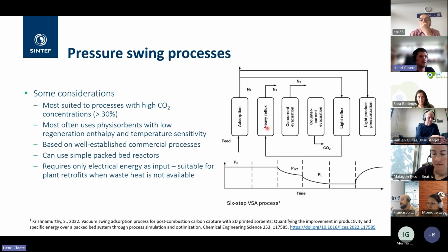So first, we can just ignore the second and the fifth boxes here. Just look at the 4 stages. What you basically do is you keep the pressure at atmospheric, you feed your flue gas, and you adsorb your CO2, and you mostly have nitrogen coming out. Then you next have an evacuation step where you draw a vacuum, and you pull off most of your nitrogen and reduce the pressure, but you stop before you start getting your CO2 out of your reactor.